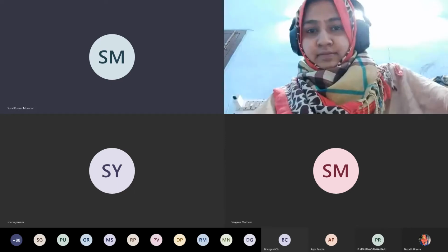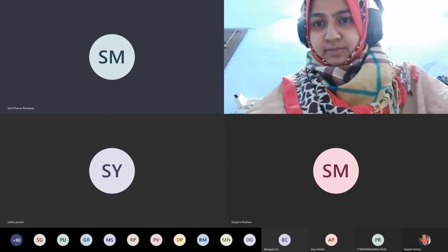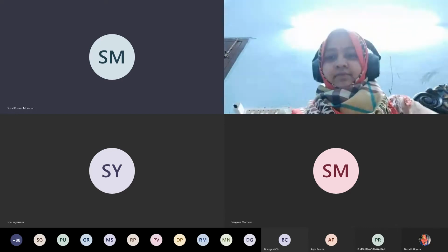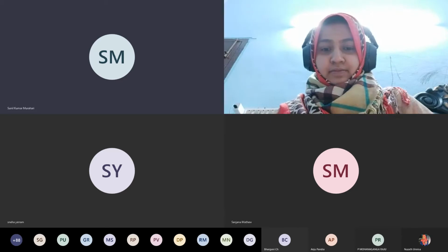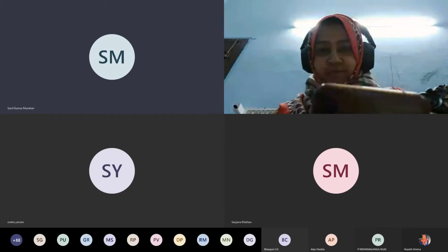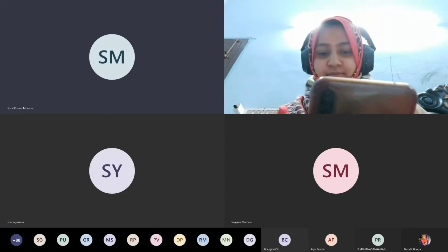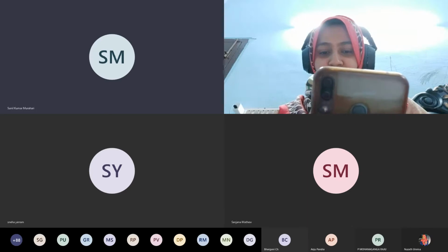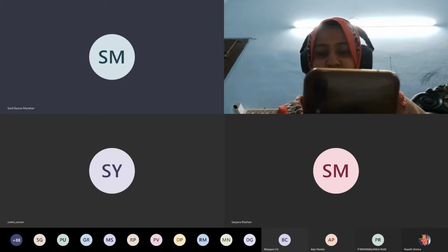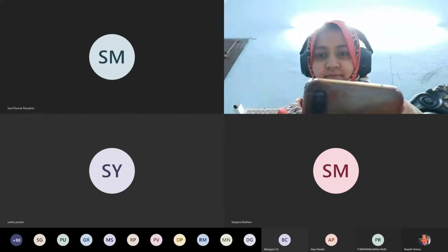One would like to have prism layers or some refined mesh near the boundaries. That is what we call the prisms. You can see the prisms have a polyhexacore kind of meshing profile. Then the next is the hexacore, the very best meshing profile one could expect, with the best aspect ratio and best quality. So the domain has been discretized in the free space.